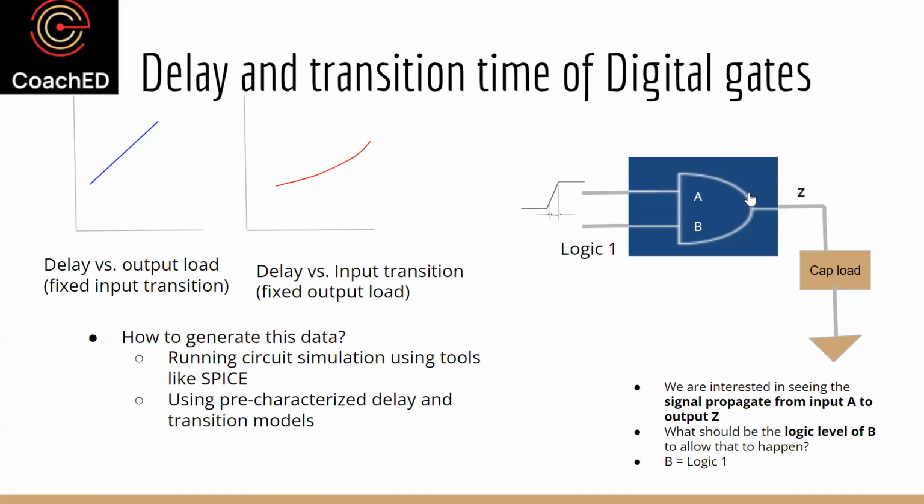Since the characterization is primarily meant for timing analysis, we will try to use this terminology, so that you can understand it if I refer to it later, especially tomorrow when I talk about timing arcs. So a timing arc basically means a relationship between a specific input pin and an output pin, or between any 2 input pins.